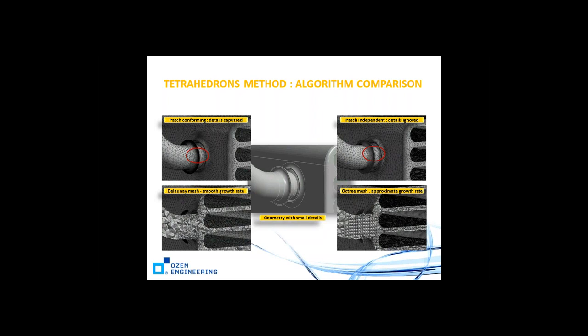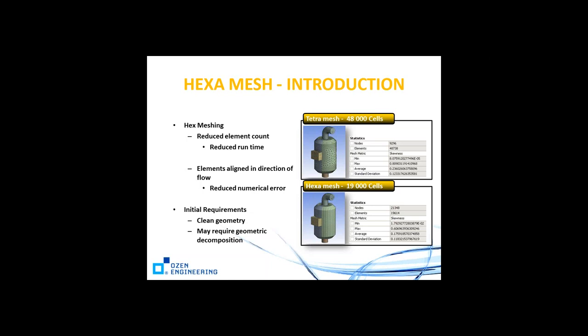So on the inside of the model, using the step meshing method, you can get two separate meshes as well, depending on which one you would pick. The default, I believe, is the Delaunay mesh, and you will be getting a mesh that looks like that. But if you'd like a more uniform mesh on the inside, you can go with the Octree mesh.